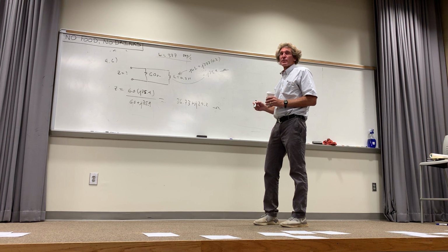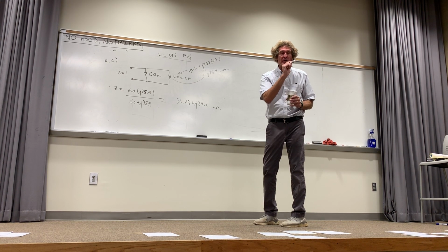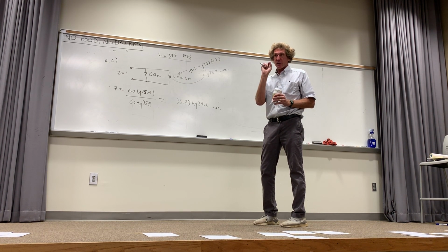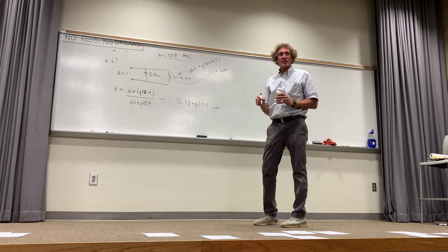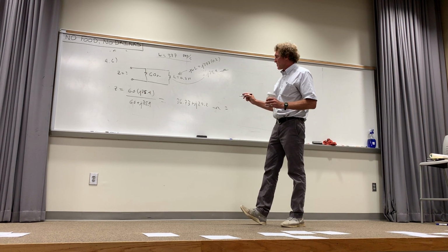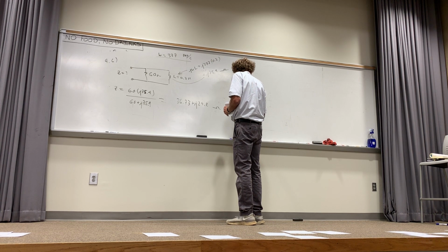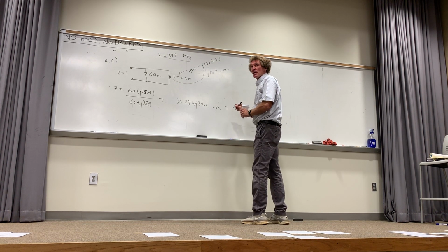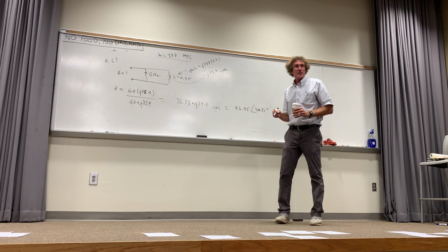Now that's a complex number. Don't clear your memory, because you can usually go to polar on your calculators with two punches of the button. If you want to go from rectangular to polar, it's usually just a function key and a stab. It'll give a magnitude and angle. Can you give that to me? It's somewhere in the neighborhood of about 46.95, at an angle of 38.5. All right, that's the equivalent impedance of that.